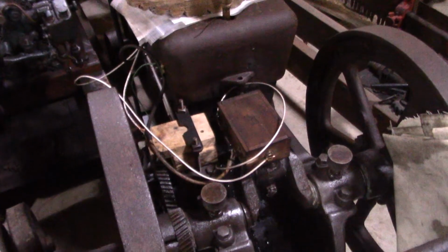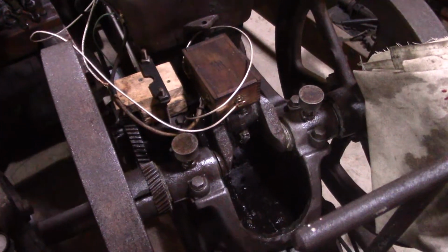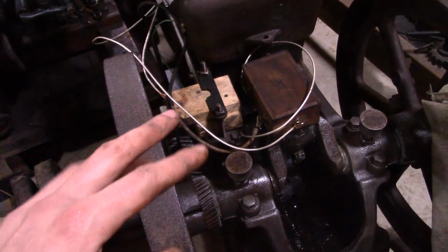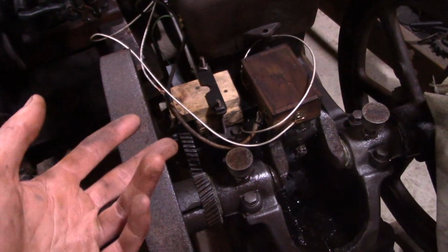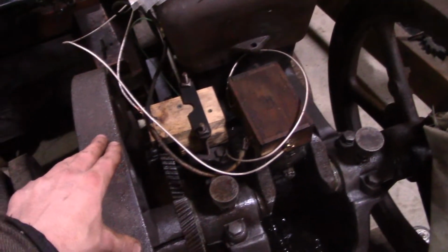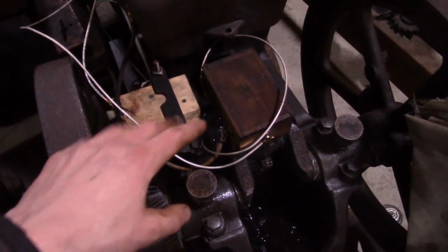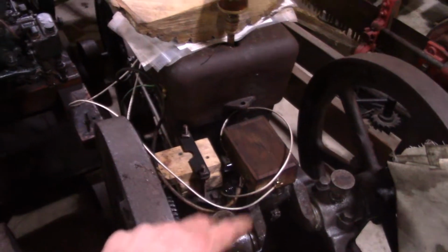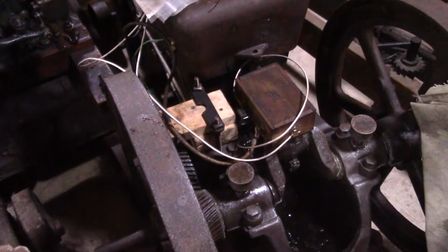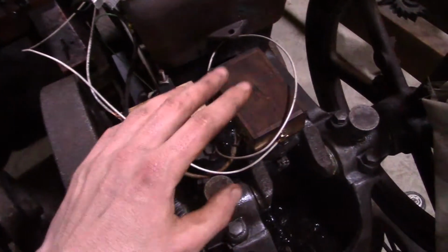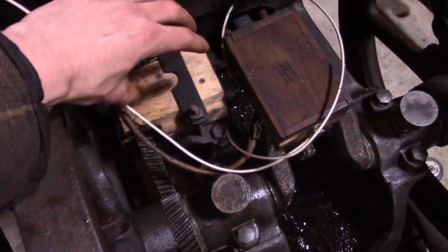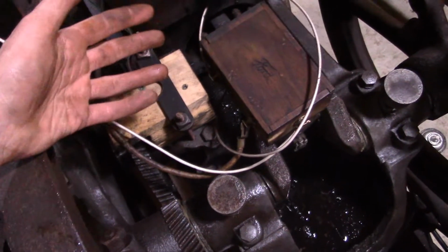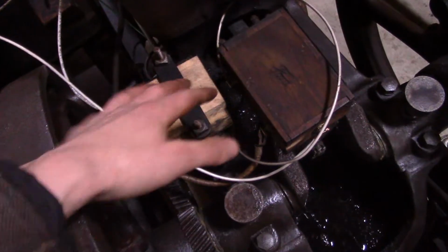Now, as far as high tension or spark plug ignition is concerned, there's generally, as far as I've seen, two sources of the spark for these small engines. One source is a battery and buzz coil, and I have it set up sort of roughly on my 3 horsepower Fairbanks Morse Model Z. It is not the correct setup. The magneto mounts right here, and that is what would normally fire the engine, but the mag needs work, so I did a quick and dirty setup with a buzz coil.